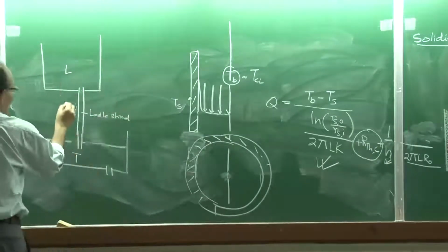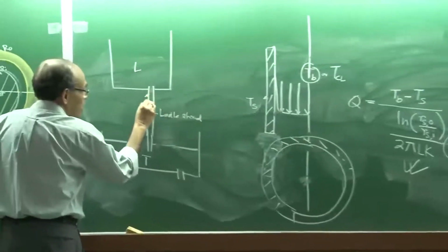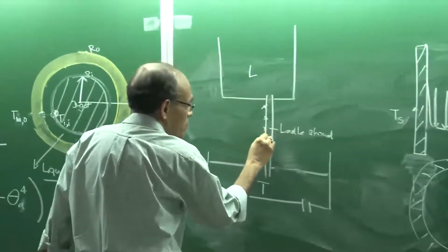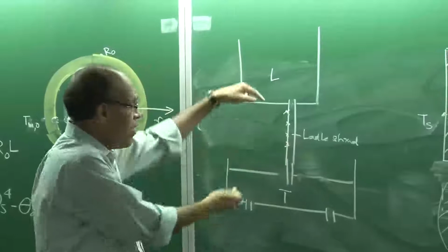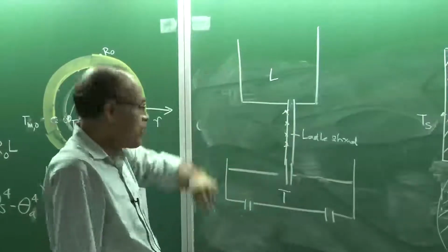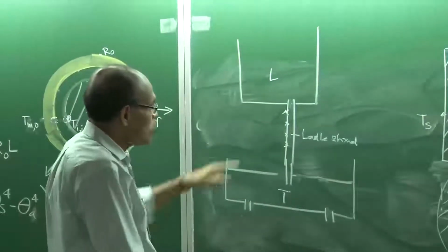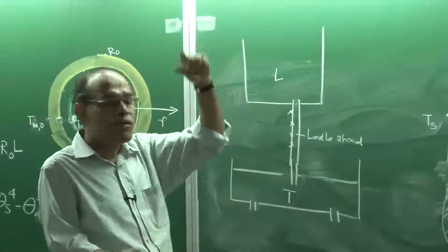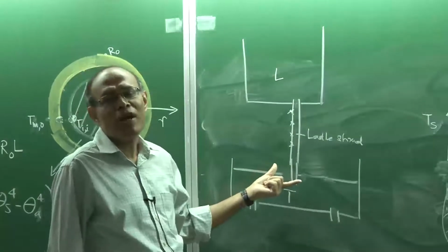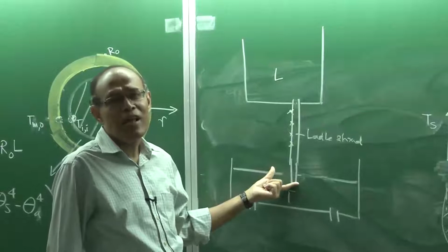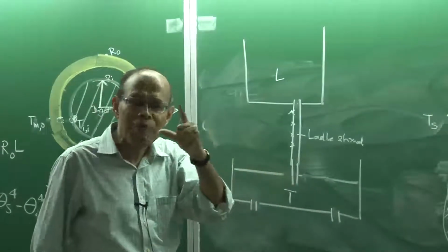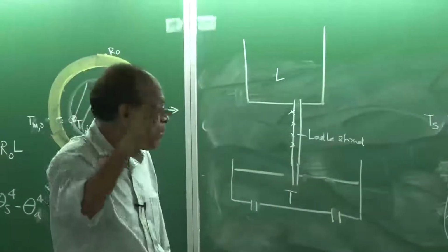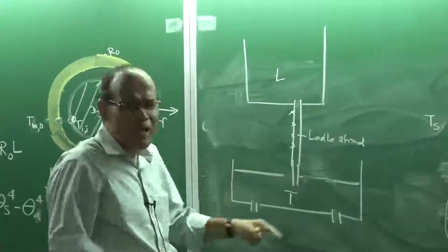Now, by measuring the temperature at different locations: the entire shroud actually is not visible in the industry because of the logistics. The shroud typically is about 1.25, 1.3 meters, which is like 4 feet. So I would say about 2.5 feet is visible. So you can measure the temperature, more or less plus minus 50 degrees.